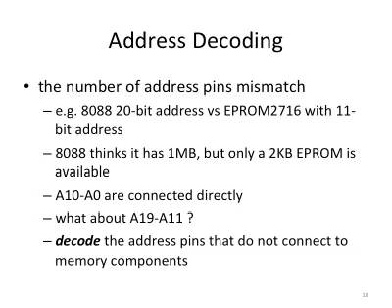And depending on where in that address space you locate this EEPROM chip, if the processor supplies the correct address, it can access the content. Otherwise, it will access something that's not there.